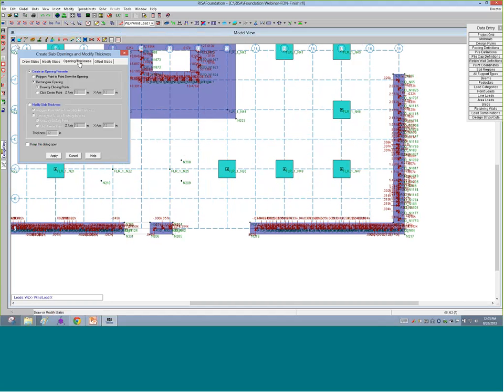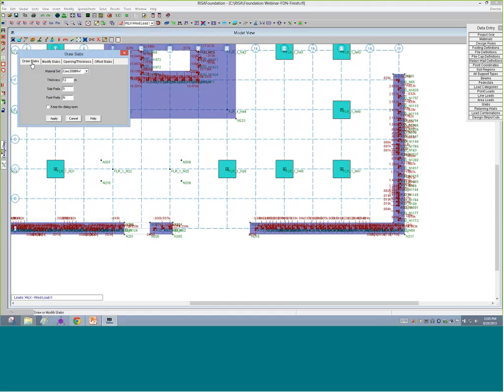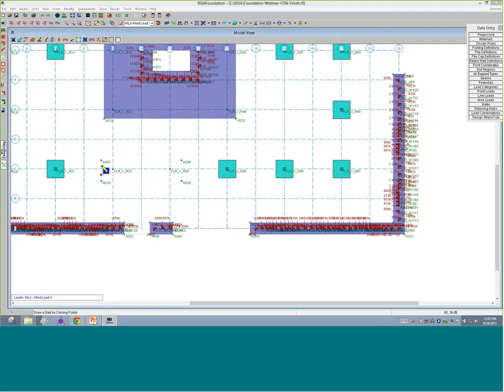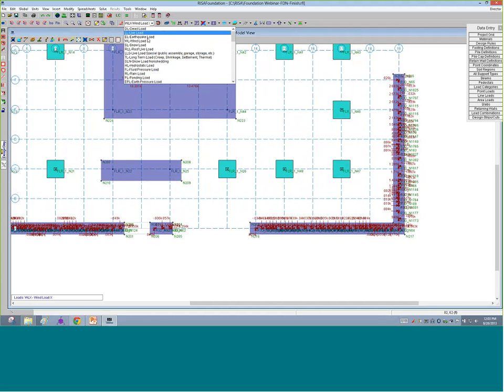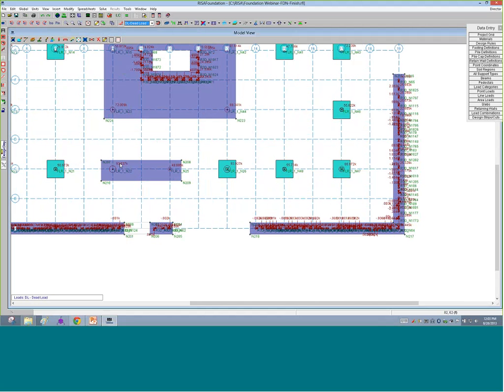And in that case, I can draw a slab instead of doing that. So maybe I'll do an 18-inch slab in this area, and I'm going to go ahead and draw it directly around these 2 footings. And you'll see there's loads coming down on those. So let's go to our dead loads again, so we can just verify, yep, those were where I wanted to have this combined footing.